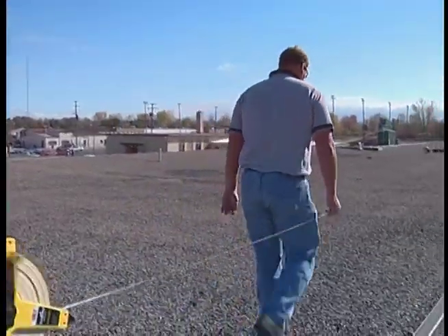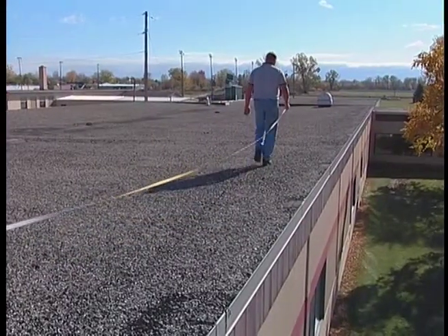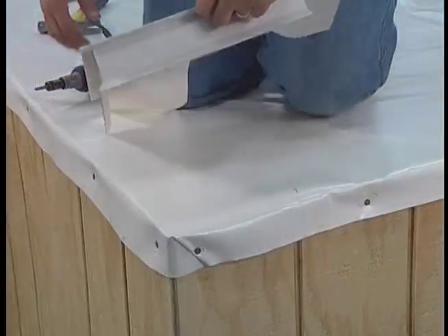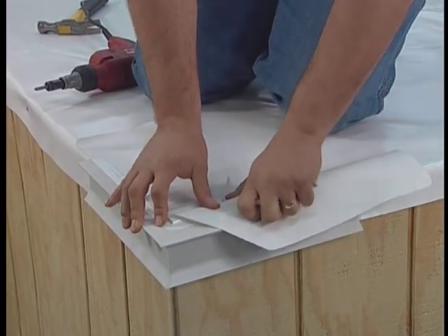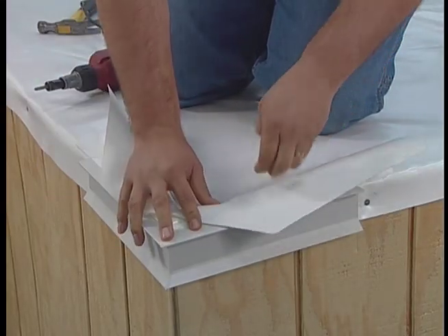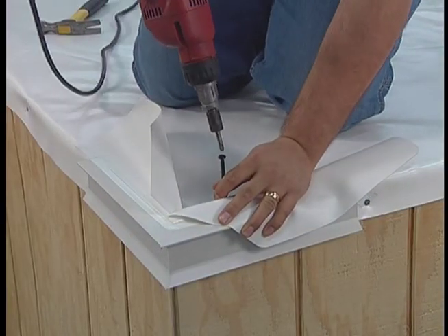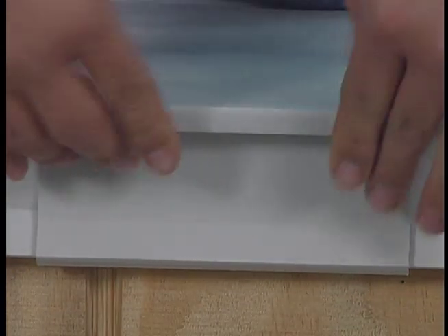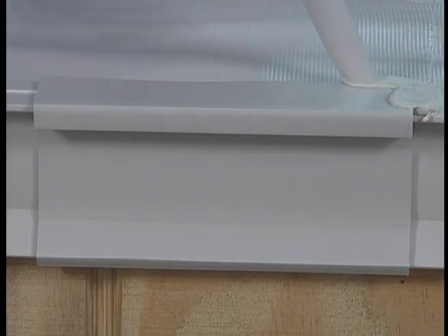After selecting the type of edge detail, the next step is to measure the building perimeter to determine the lineal footage needed. For Duro-Last vinyl drip edge and gravel stop products, it is recommended that you install Duro-Last 90-degree outside corners. Be sure to count the number of corners on the building and order them accordingly. Duro-Last will provide a cover clip for every 10-foot length of vinyl edge detail ordered. If you are going to make additional cuts at the job site, you will need to order extra cover clips.